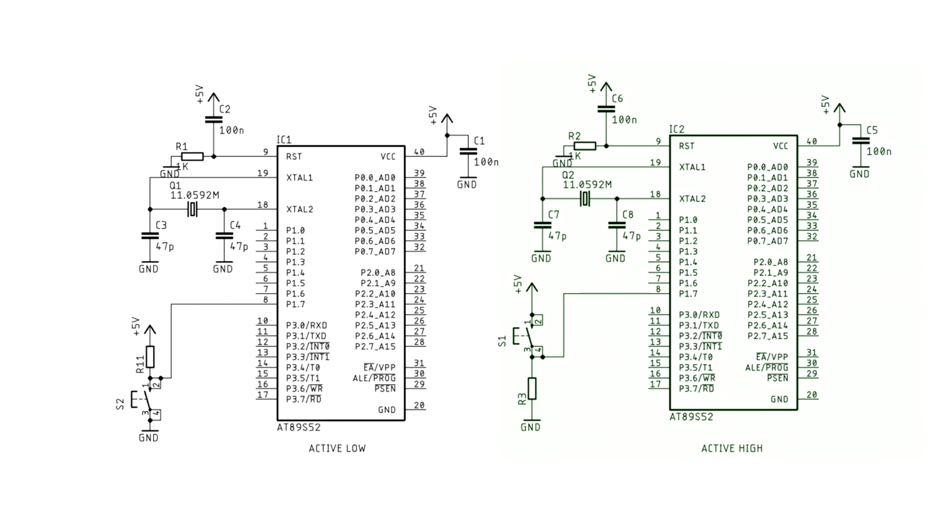the microcontroller. With active low configuration, the switch is connected to the MCU with a pull-up resistor, a resistor from the MCU pin to VCC, while the other end of the switch is connected to ground. It will give a low logic to the microcontroller when asserted. The pull-up resistor ensures a high logic when the button is not pressed, and a pull-down resistor ensures a low logic when the switch is not pressed.